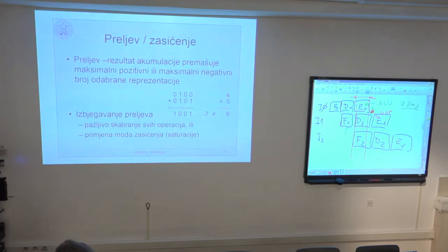And this saturation is automatically supported at the hardware level. So you simply activate this saturation mode, then after that, all of the ALU instructions are performed with saturation. The same is for the negative side. So if I add two negative values, and if this sum exceeds the largest negative value, it is automatically saturated to the most negative value.